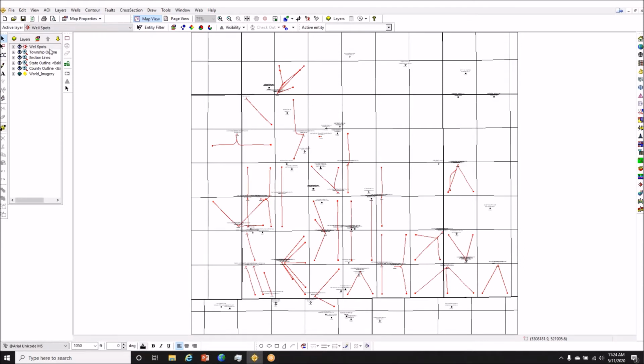So the first aspect of that, as I mentioned before, is cleaning up your layer list. You want to make sure that the list only contains layers that are going to be used for the final presentation, and not any other layers that are just there on the map but hidden for later use or anything else like that. Again, some of those will still be loaded into memory, whether they're displayed or not. So in the interest of rendering those objects, you want to limit that down to a smaller condensed set of layers that are easier to work with.